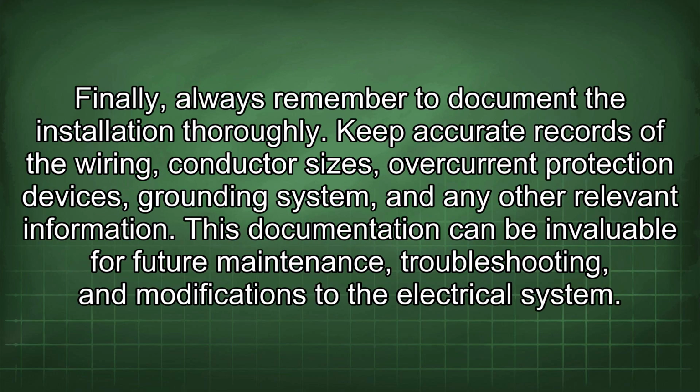Finally, always remember to document the installation thoroughly. Keep accurate records of the wiring, conductor sizes, overcurrent protection devices, grounding system, and any other relevant information. This documentation can be invaluable for future maintenance, troubleshooting, and modifications to the electrical system.